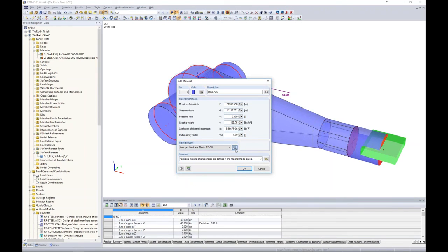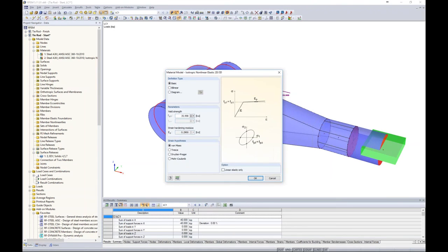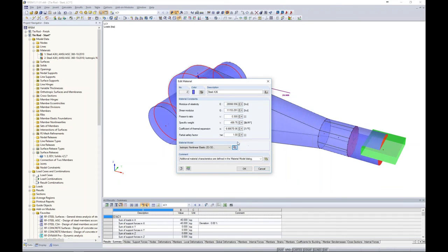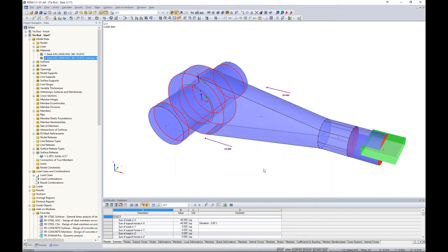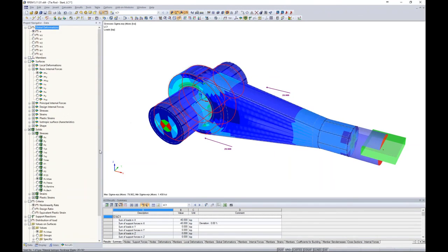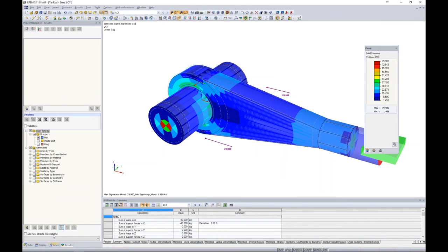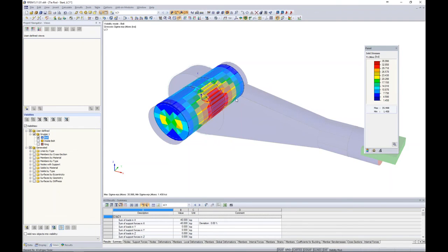So for example, you can see here in our details, which if this opens up, I don't know why there's a little bit of a lag time. It must be the FE elements, but we can see here the yield strength is set to 36 KSI more or less just from our steel A36 material. So now when we take a look at the model and we ran our analysis, which is what we just saw, we can turn back on our results and take a look at maybe our view of just our bolt. Again, nothing is going to be above this 36 KSI.